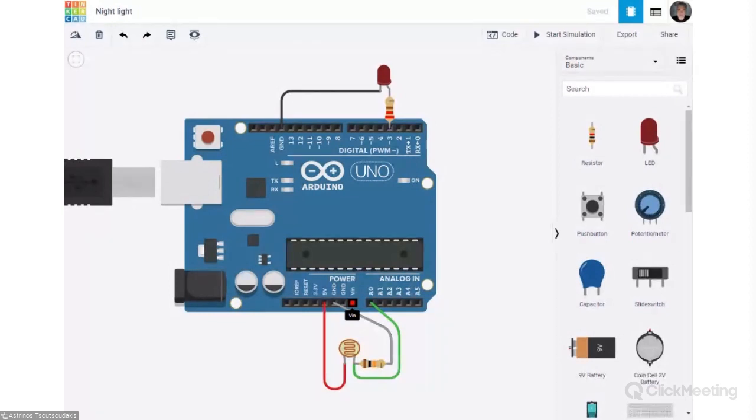Or if you have a stabilized power supply, you can supply 5 volts directly. Of course, if the USB cable is connected, you can get 5 volts from this terminal. And you can use a barrel connector, a 2.1 millimeter connector, and you can connect a 9-volt battery by using this.